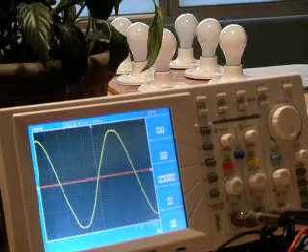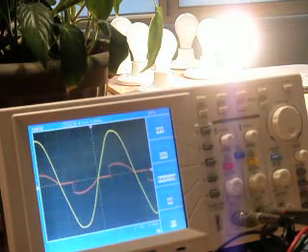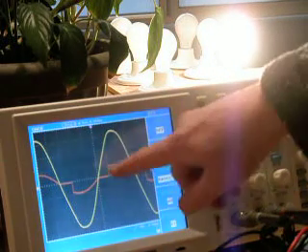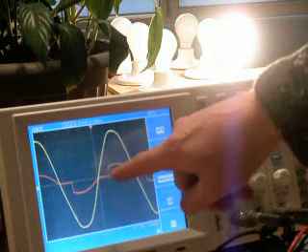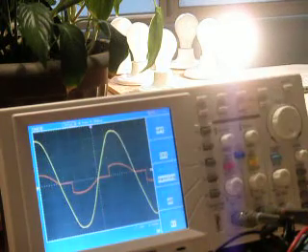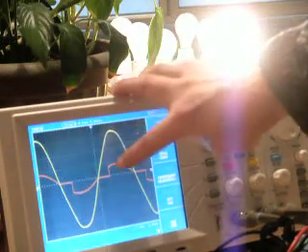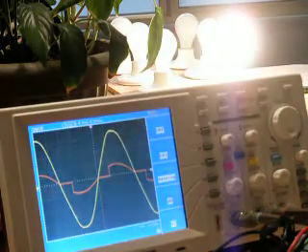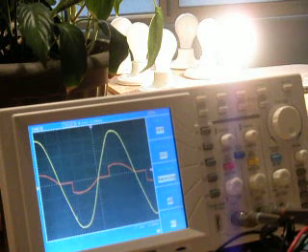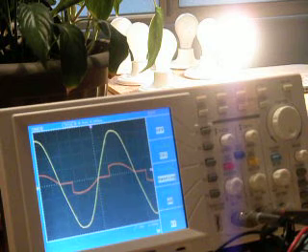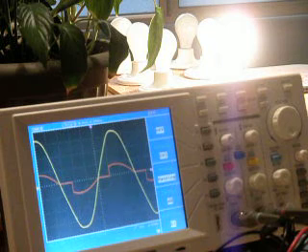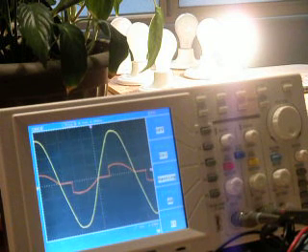And we can see it's quite different. So there you have it. Lamp dimmers actually function by chopping up the current waveform. And when you do that, you get a noise on the voltage waveform and also on the current waveform in the form of a little spike. And that creates really bad harmonics on the system. And you get a lot of emissions coming off the system in the form of electromagnetic radiation and interference. So let's turn on our second lamp dimmer and see what happens.